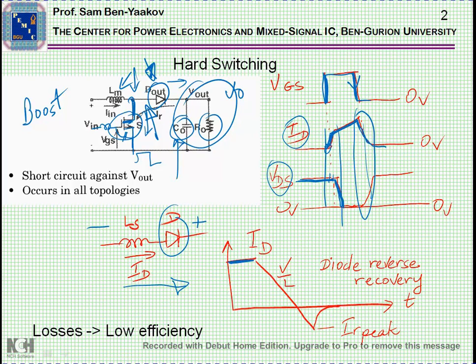Now, you might assume that as the voltage reverses, the current will stop, but it does not. In fact, what happens is that there is the residual current of the leakage inductance, and there is no escape. Each branch will have some leakage inductance. This residual current goes down because of the polarity of the voltage now. It'll reach zero, and in fact will go negative.